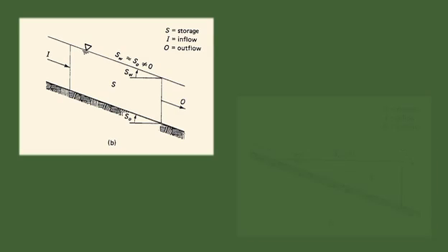Thus, it would appear that the kinematic wave approach is a better model of the physical process than the storage concept. Further analysis has shown, however, that while the kinematic wave lacks diffusion, the storage concept does not. In this sense, the storage concept remains applicable for cases featuring significant amounts of runoff diffusion.